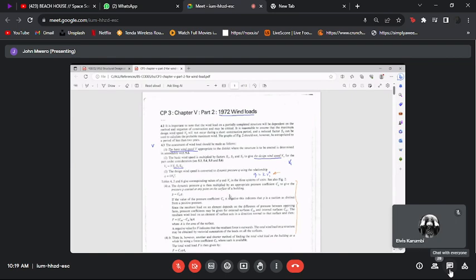This wind speed is usually derived from meteorological data and statistics. They collect the data and do statistics to say that generally in this area you can use this kind of wind speed. That wind speed, our starting point, is referred to as the basic wind speed and is denoted in this standard as uppercase V.